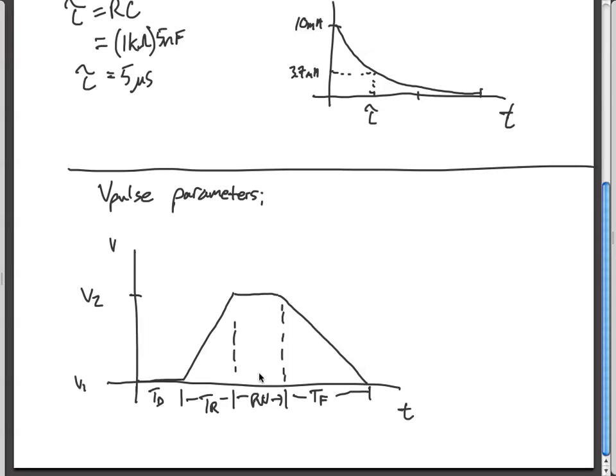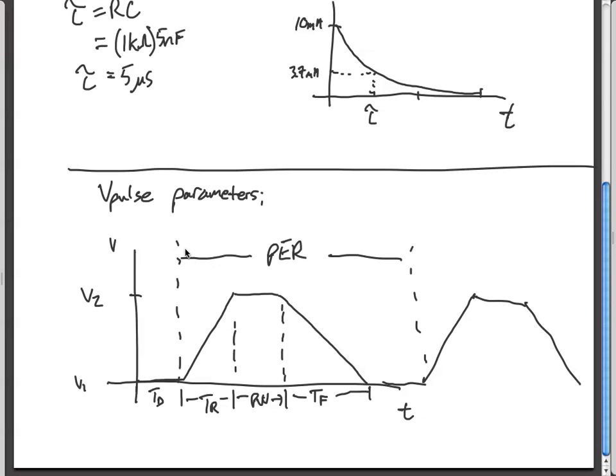And if you wanted this whole thing to be periodic, you can specify a period where, let's say, this were going to occur again. And I believe that's from the starting point. Oh, let me redo that, actually. And this would be the period, PER. Yeah? So those are all the things you can define about this particular pulse source. It gives you a lot of control.